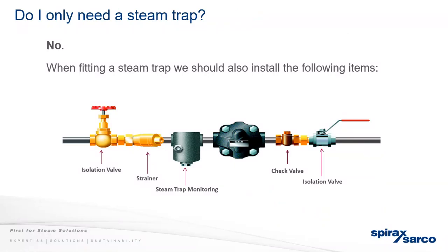The APT is a lower capacity than the MFP, but both of them clear quite a large amount of condensate. I think we're talking about 2,000 kilograms an hour or something like that on the MFP, certainly. I'm not too sure on the APT, depending on the differential pressures and the back pressure. Yeah. So we do mechanical pump traps. Any other questions? No. Okay.